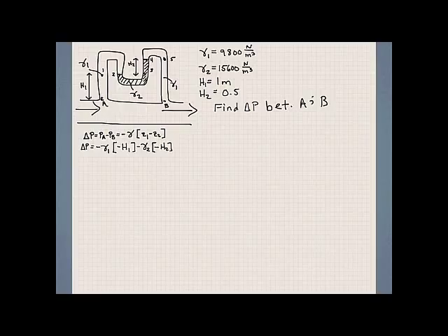Okay. The next point we have, again, is a fluid gamma 1. So I'll go ahead and write that, minus gamma 1. Now we have to decide what the sign is going to be. Now remember, the next place we start off is between the interface of our new fluid, which is the mercury, and point B, since all the fluid is the same throughout that tube.